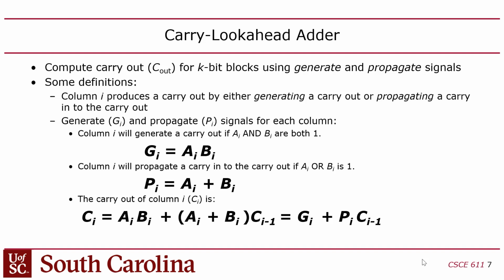So in other words, you still use a full adder, but instead of getting its carry-in by passing data all the way through the columns to its right, you can pre-calculate the carry-in for each column, right? It changes how you get carry-ins. Does that make sense? Okay, so the way you do that is there's this notion called generate and propagate.